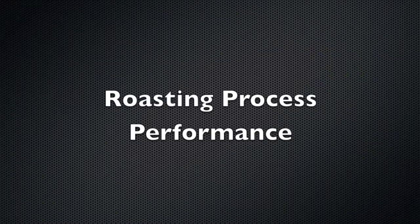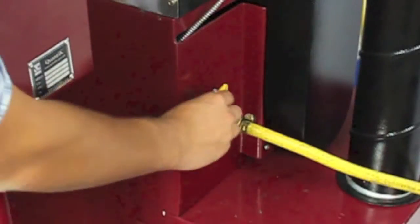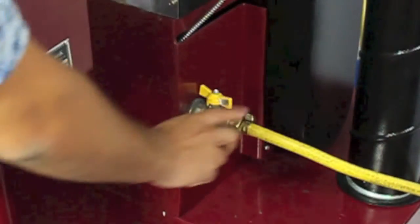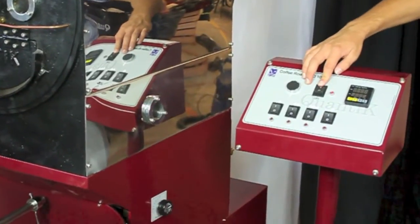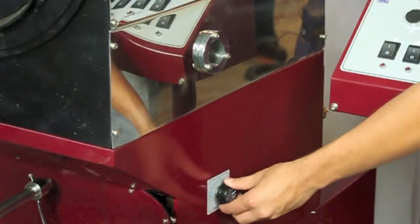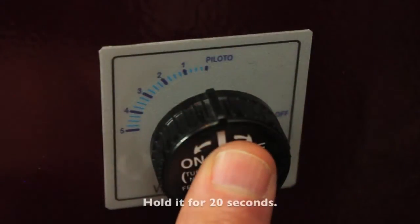Roasting process performance. The first step is turning on the roaster and preparing for roasting. Open the yellow valve of gas passage. It must be in direction of the pipe. Push the upper on-off switch. Rotate the regulatory and safety valve from the right to its central position.